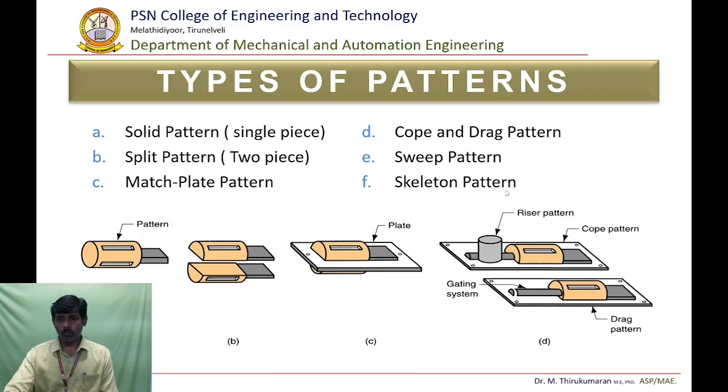Next one is the cope and drag box pattern, which is quite costlier compared to the solid, split and match plate patterns. We use the cope and drag box pattern because we can develop a large number of samples as well as more complicated shapes.